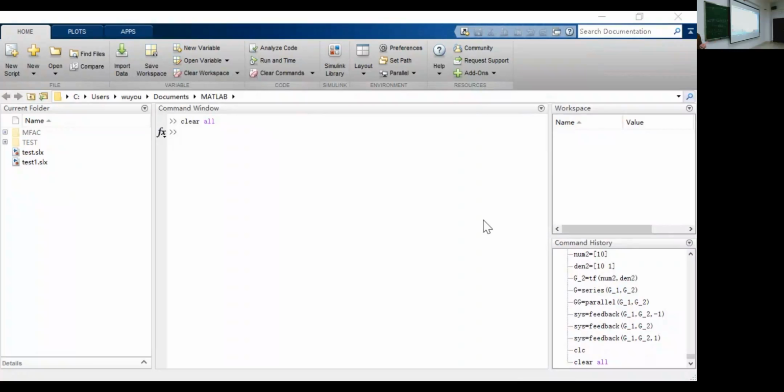Okay, let's have here a step time. Maybe we change it to a bigger number, maybe 20, okay? Initial value means if the step doesn't happen, what was the initial value here? Maybe we set it to 0. And the final value is 1, meaning the whole step value is 1. So the step is a unit step.